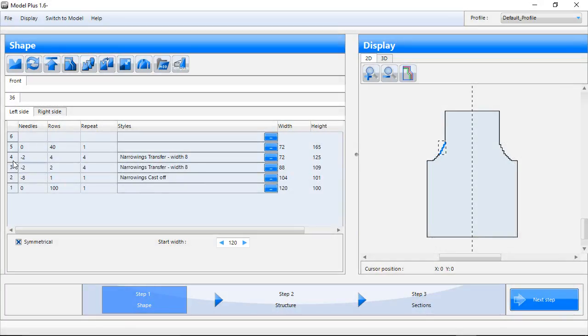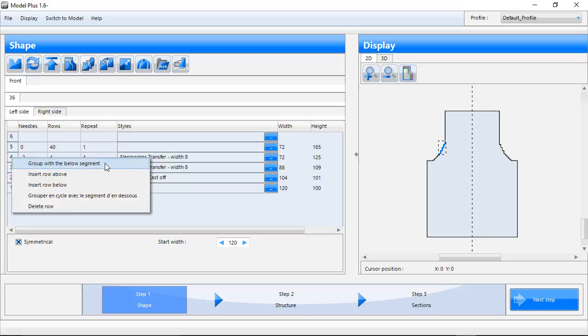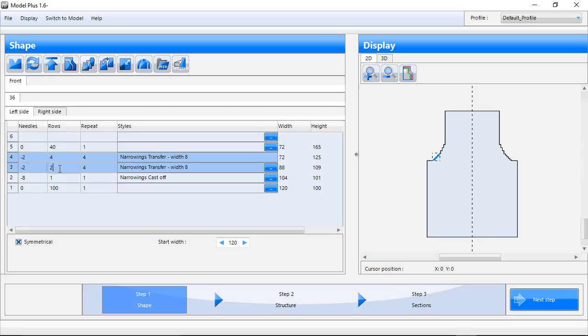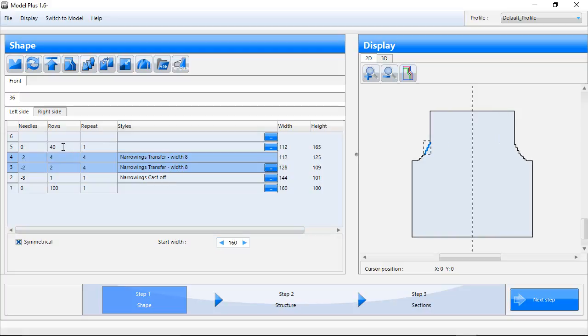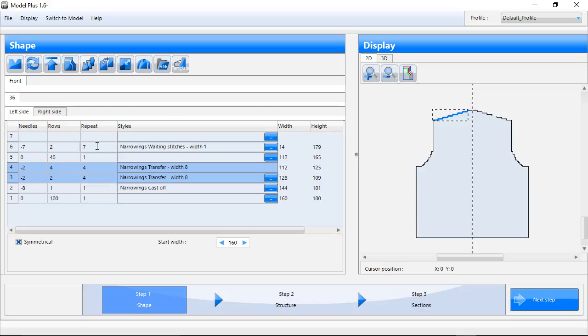Several technical segments visible in this grid can be grouped into a same logical segment. When several technical segments are grouped into one logical segment, it's visible with the specific color alternation. Each row of the grid refers to a technical segment, whereas there is only a different segment realization style for each logical segment. For that reason, the Modify Realization Style button is only visible on the first technical segment of the logical group. If the realization style of a logical segment is modified, the modification will automatically take effect in all the children of the logical segment.